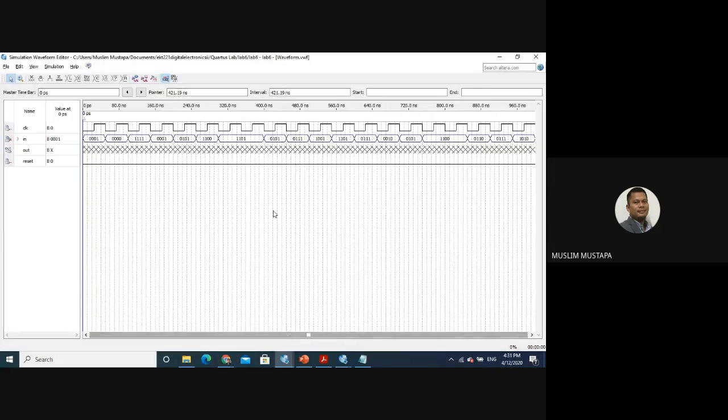Okay, if you see here, I'm purposely doing 2 examples of 1101. In this case, I'm doing 1101 at 2 clock cycles, right here. And here I'm doing the 1101 at 1 clock cycle only, because we want to see the difference. Now let's run the functional simulation.